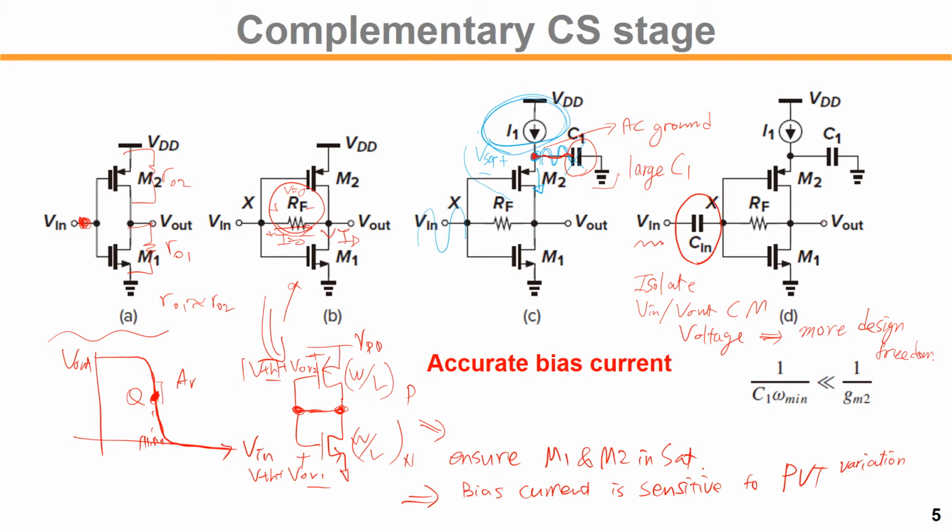Another requirement for sizing for AC coupling at the input: this looks like we have a finite impedance G in, so we have a C and finite impedance, and C results in a high pass filter, so the signal must pass through this capacitor properly for the given signal of interest.